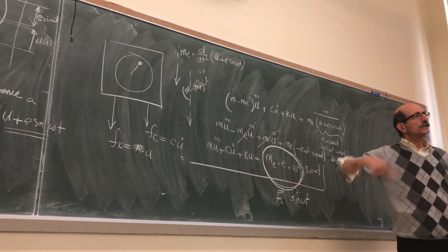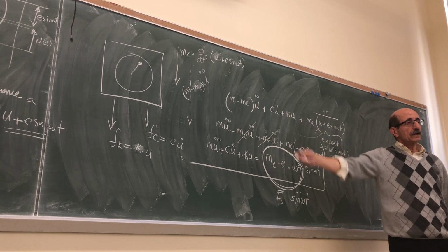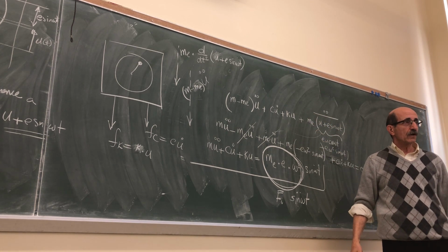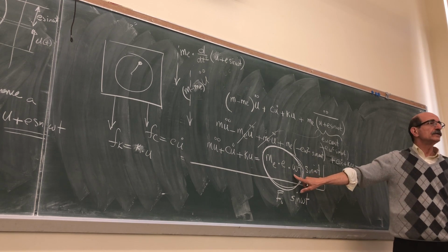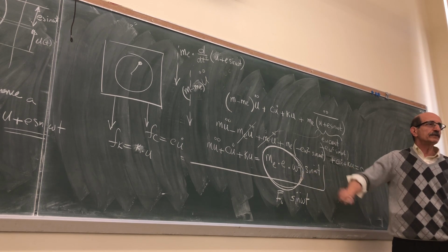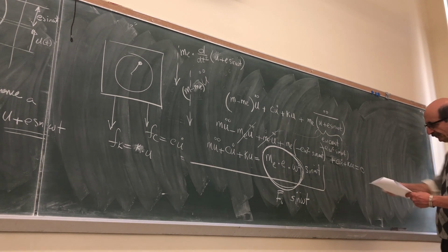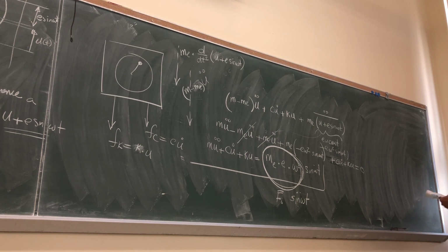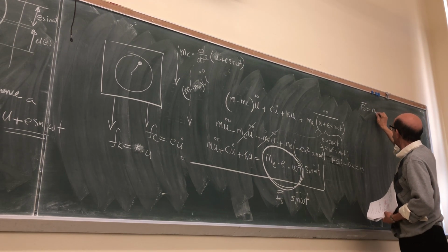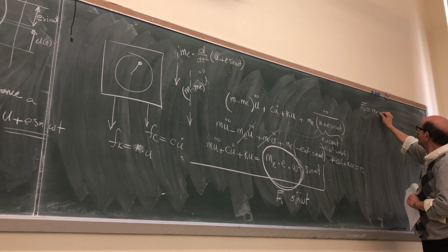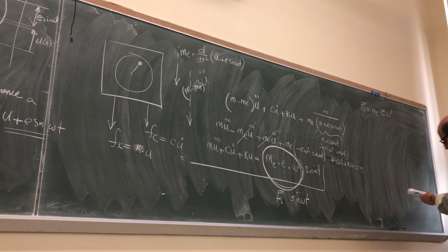In contrast to the regular forced vibration, harmonically excited system that we saw, the amplitude of the forcing function is dependent on the frequency. Okay? You can simplify these. In other words, if I write F0, which is m_e times e omega squared, right?